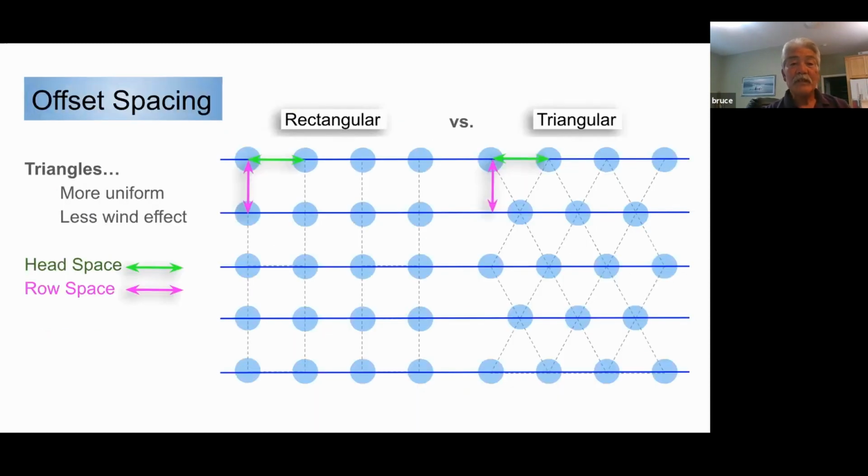Okay. Some other tricks of the trade. I'm not going to talk too much about rectangular, but triangular spacing is a more effective spacing method than, say, a square pattern. Triangular means an equilateral triangle, so if you go between two heads on a line, the distance from the point halfway between the two heads to your sprinkler head itself would be the same distance. So if you were at a 50 by 50 spacing, the distance from the two heads to the point on the next line over in that triangular fashion is 50 feet. That's the important part. Next.